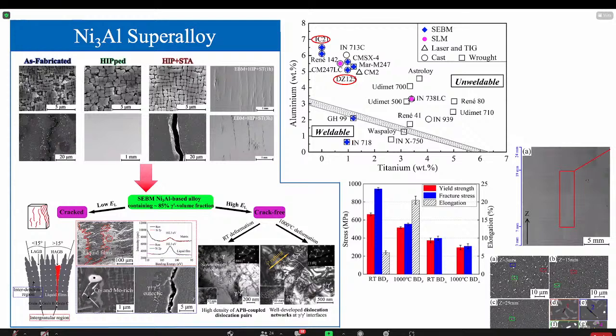And this kind of gamma prime, depending on the composition range, could cause tensile residual stress. So this is what we thought: when you give this heat treatment, you generate this tensile stress because your process parameters haven't got to the stage to generate a very good metallurgical bonding. So with such a cooling stress, you could just open up this crack in the materials.